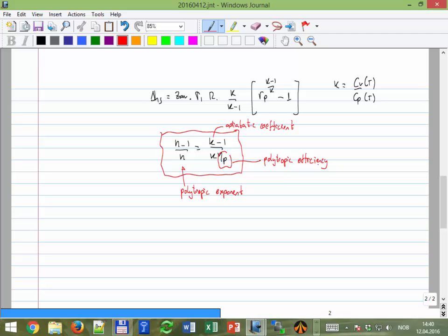And this K we can also calculate. This is a formula that is typically used in compressor design, and it's an approximation, but it actually works quite okay. For hydrocarbon gases, this K has the following expression: 1.3 minus 0.31 times the specific gravity of the gas minus 0.55, trying to relate the deviation with respect to methane.